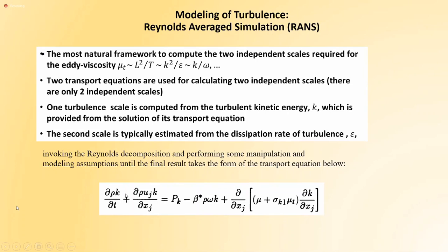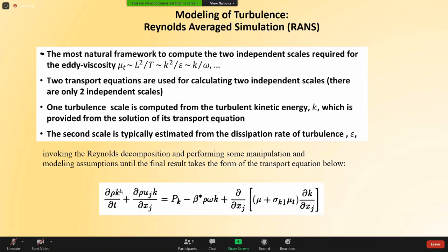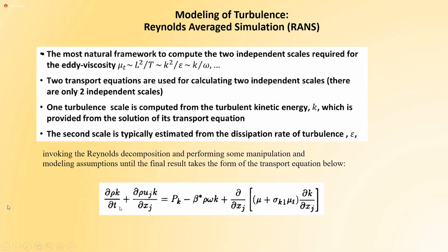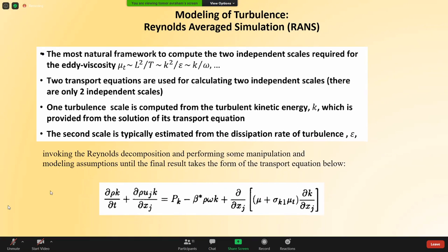But what we do, it's not a turbulence course, but after we do the whole decomposition, we get a lot of terms which are like triple correlations between perturbative velocities. What we want is not to have any perturbative velocity in the equation.